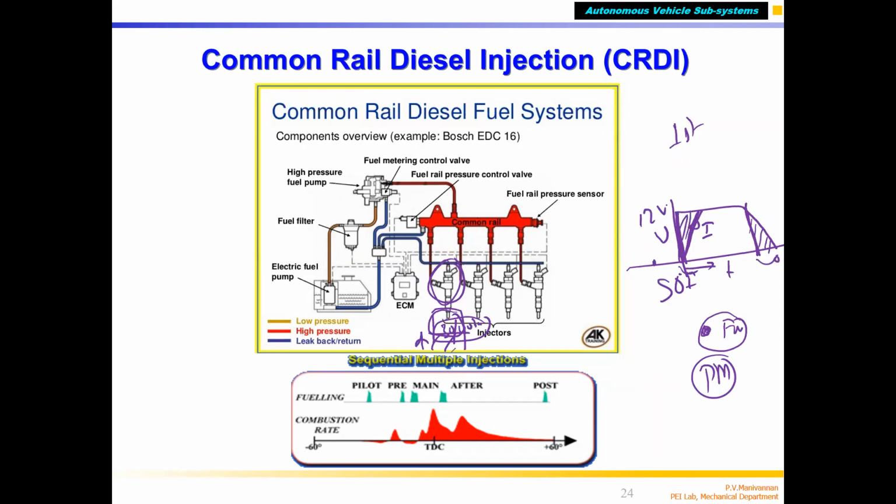During this time a pressure drop happens, so the fuel will not become fine droplets; bigger droplets mean particulate matter. That is why in CRDi engines, instead of conventional solenoid injectors, they are now using what you call piezo injectors.